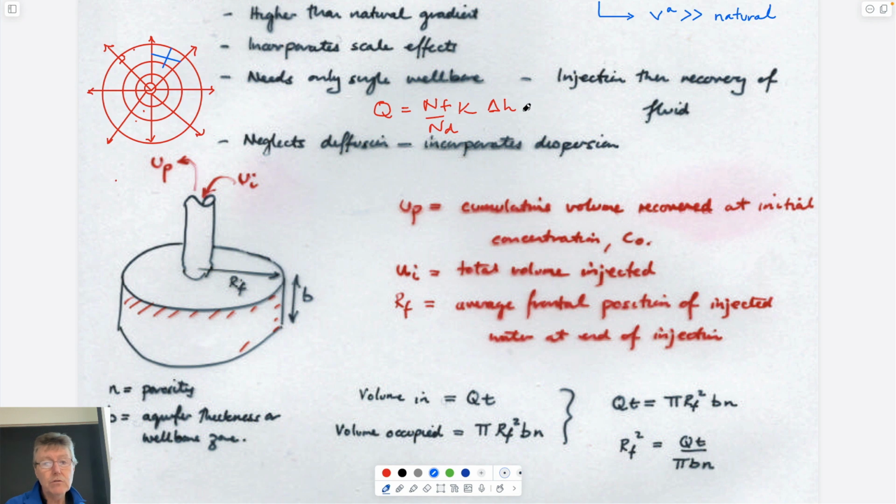So this one would give you the volumetric flow rate is equal to number of flow channels, 1, 2, there are 8. Number of drops between the well would be 1, 2, 3. Whatever the hydraulic conductivity is, and whatever the head drop is between the outside and the inside, gives you your flow rate into the well. Incredibly powerful.